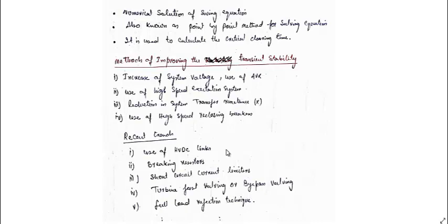So there will be no sine delta. There will not be any curve which has a portion where the electrical power decreases, as in the case of AC, because in case of AC electrical power decreases for delta equal to 90 to 180 degree, which is the prime reason for the instability of the system. In case of HVDC there is no such case.